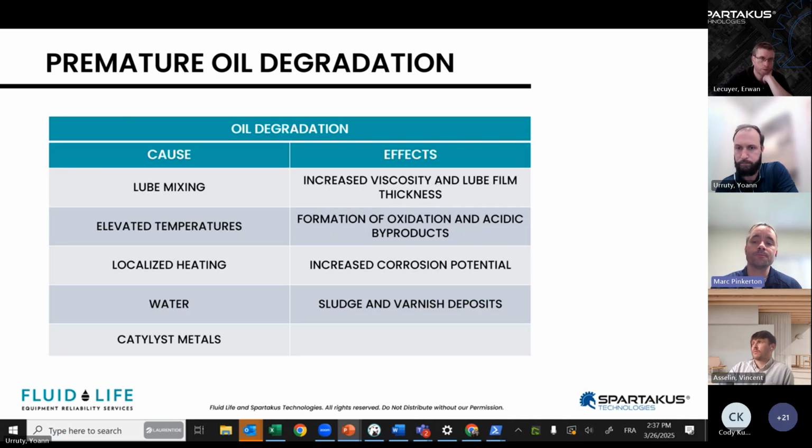When that occurs, you're going to increase the chances of your oil becoming corrosive, and of varnish and sludge deposits. That can mean a lack of functionality if you have valves opening and closing, and poor heat dissipation too. One of the oil's jobs is to dissipate heat from the components. If they're covered in deposits and we can't make that heat transfer, that could be a positive feedback loop as well.